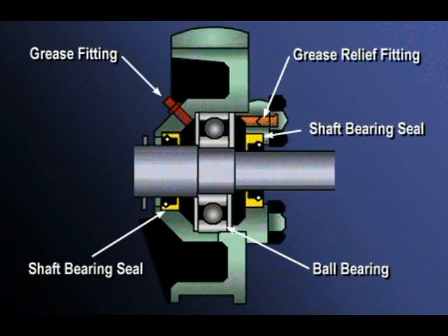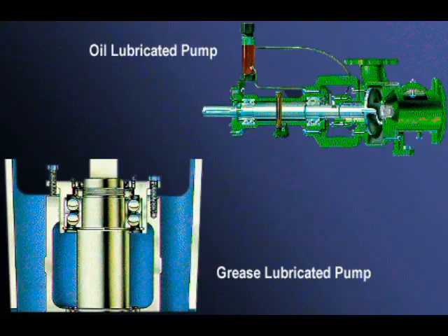Shaft bearing seals are associated with the shaft bearing units and are used to keep the lubricant in and moisture and dirt out. A wide variety of bearing seals are manufactured, so it is important to check with your manufacturer's literature before replacing any seals on specific units.